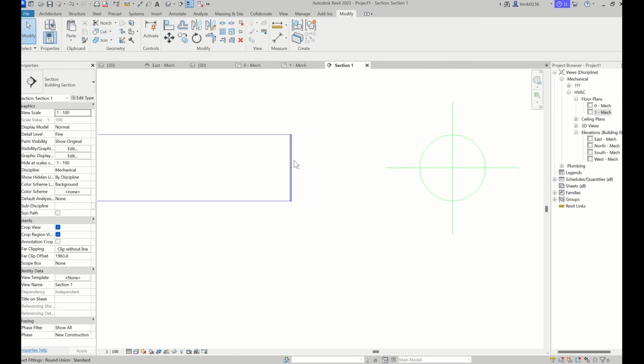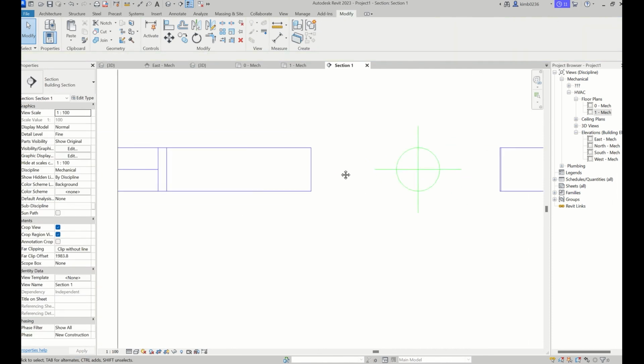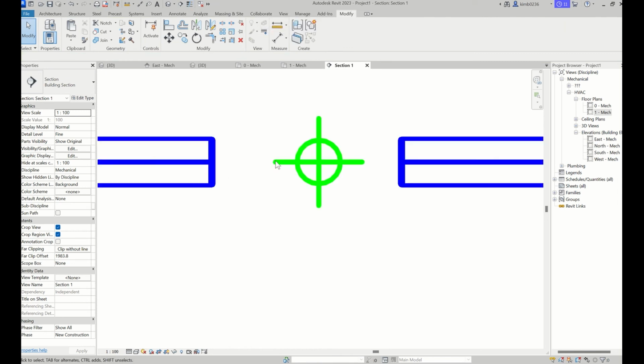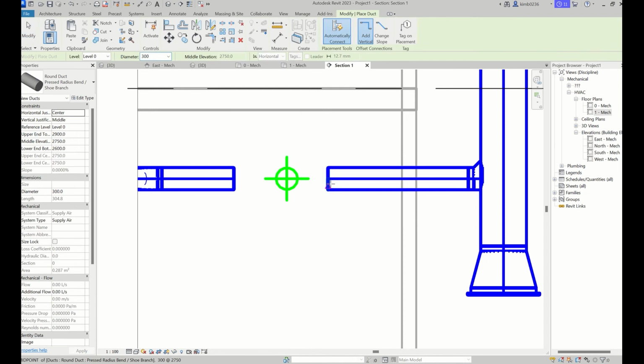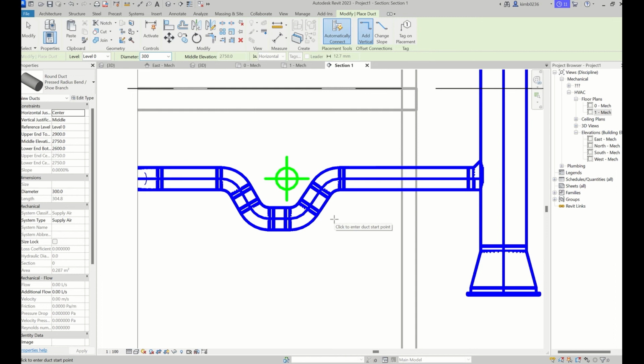Let's go thin lines. You can see that it's automatically put a cap on the end. So let's delete that. Delete the other one too, I guess. Thick lines, why not? We'll select it. I've used CS for create similar and go from the center point. We'll just move it so it's coming down, across, and up again, and now it's got a nice little path around.